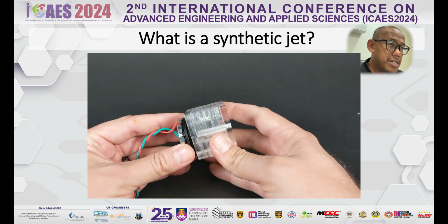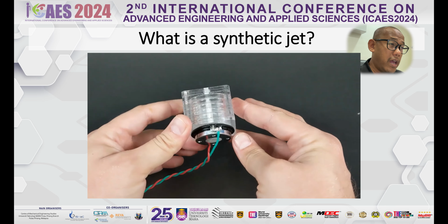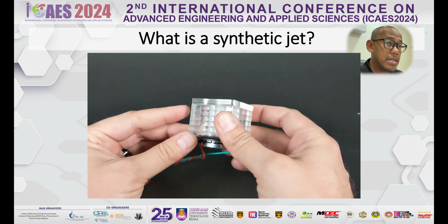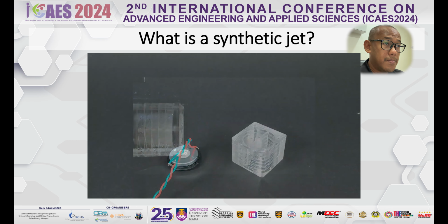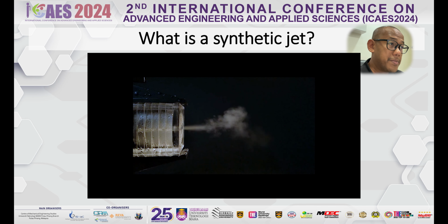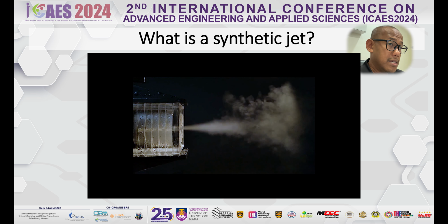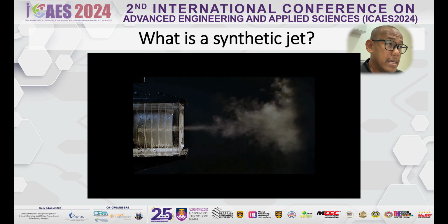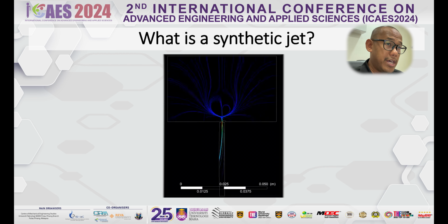A synthetic jet is a fluidic device that generates a jet of air or other fluid without the need for external supply lines. It operates by using a diaphragm or membrane that moves back and forth within a cavity, drawing in fluid through an opening and then expelling it to create high velocity jets.